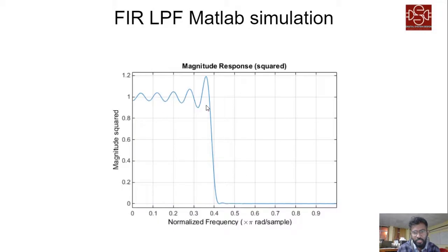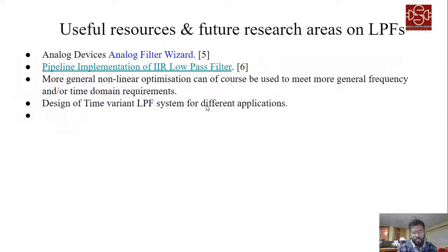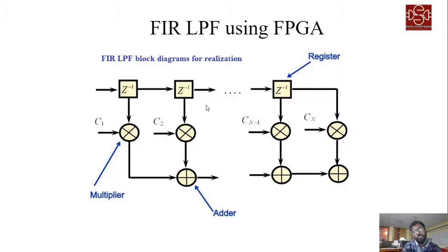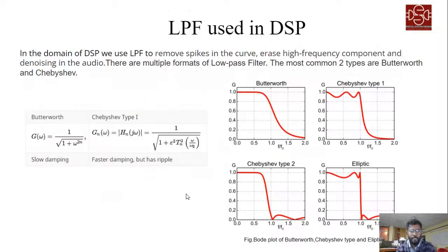Just one thing to mention: for implementation of the FIR filter, Z inverse is the register you can use in the FPGA implementation, this is the multiplier, and the summation is the adder here. So from this presentation we can link with the FPGA.